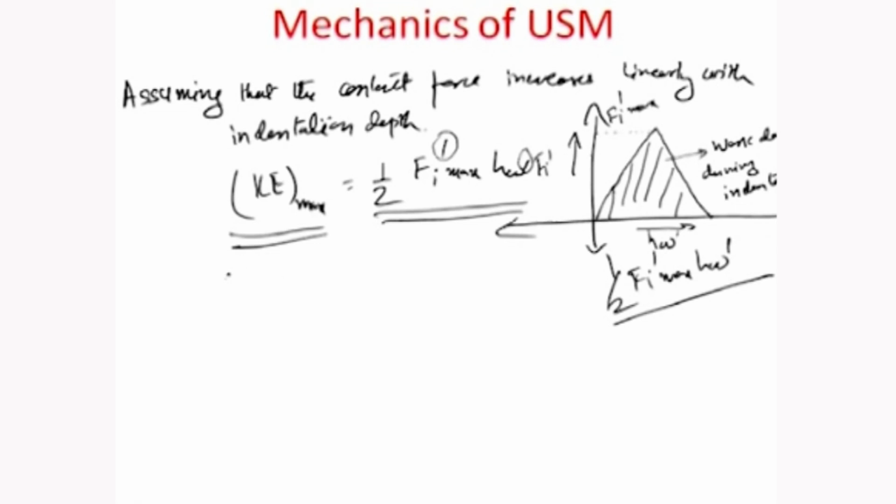So sigma W is also equal to the hardness of the workpiece. These are all flow stresses, related to the maximum force at that instant when the indentation had gone maximum, so Fi dash max per unit area.